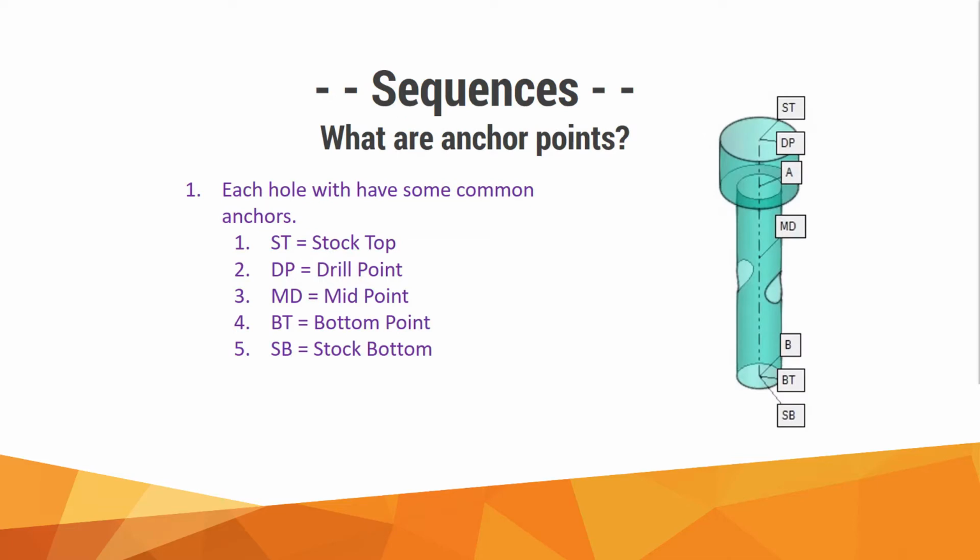What are anchor points? This is something that we cover in the intro to auto drill. We highly recommend you check that before going through these sequences. But something you're going to see in every group when you're doing these procedures is the standard anchor points. ST is for stock top. DP is for drill point up at the top here. MD is for the middle point, so the very middle of the geometry of the entire hole selection. BT is bottom point, and ST is stock bottom.